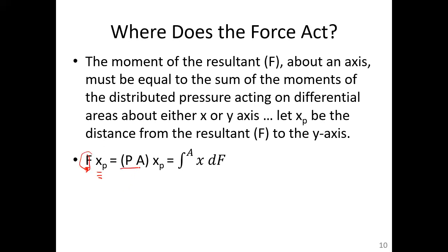We expand F to PA, and this is xp again, and this would be the moment arm of each little differential strip dA with each little force dF acting on it. And if this is the y-axis going into and out of the board, dF has some moment arm x.